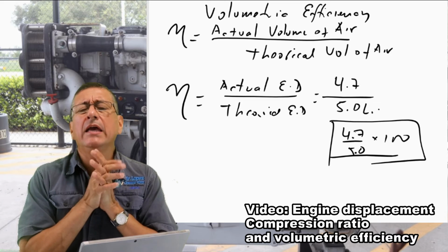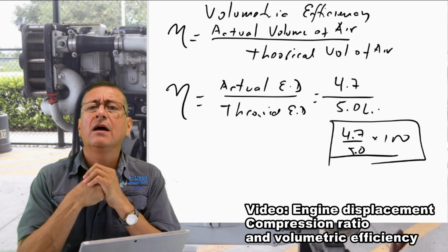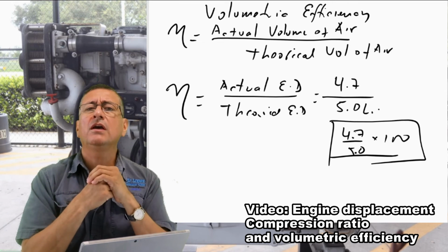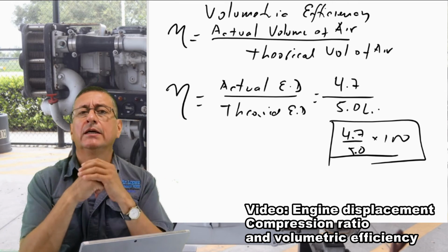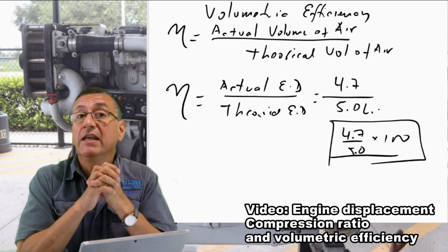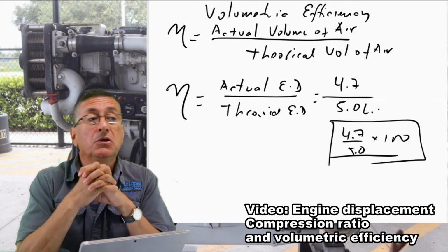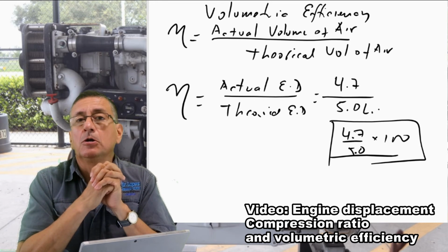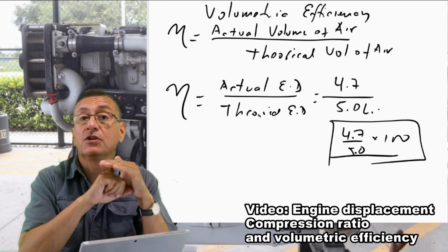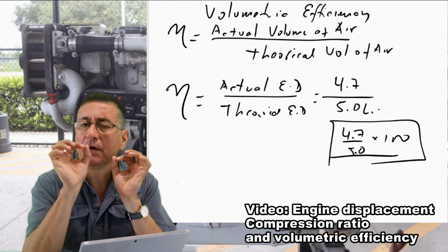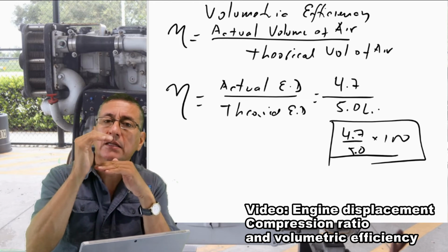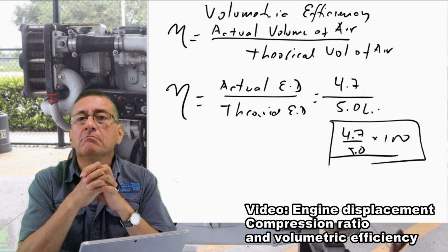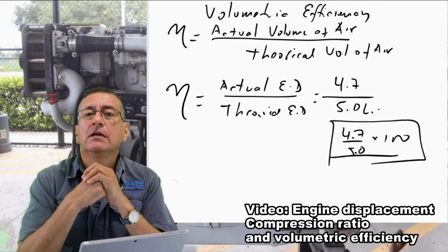Why is the actual amount of air that the piston sucks in when it goes down a little less than the theoretical? Because you have leaks, because your engine has 200,000 miles, because the valves don't close properly, because you have a small leak between the head and the block at the head gasket, because there are too many leaks, because there is dissipation of heat.